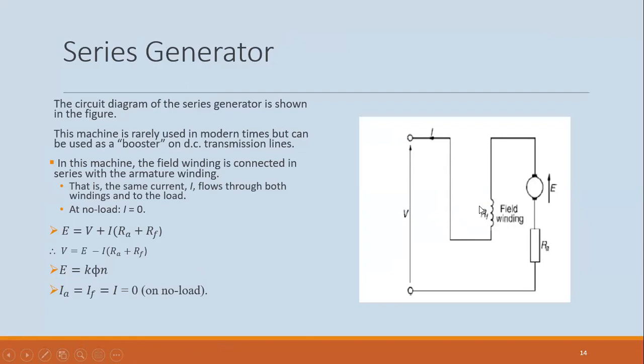But what they have done basically is to show you that the field winding close to the armature is producing a flux. So the flux is what is going to be causing, when the armature conductor is turning, an induced EMF across here. But as I say, it's not necessary to draw it like that. Some books do, and it actually shows you the flux flowing across.